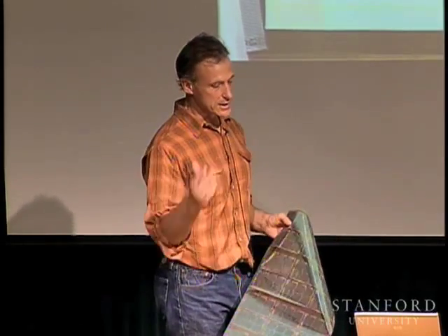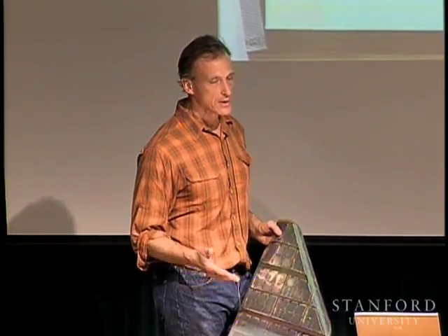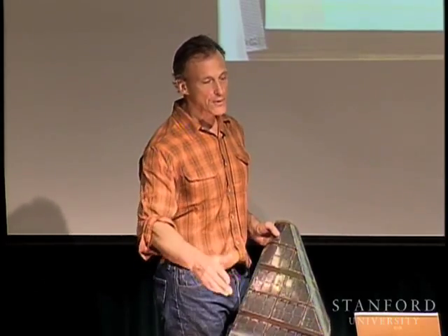Yeah. So wait, masters. Okay, the terminology here. The master is the fundamental thing that we cut into either on a glass plate or on a silicon wafer, and those don't wear out. What wears out is the actual elastomer that we're using to produce the many cyclical impressions. As a target, we've developed proprietary materials that can last for 1,000 impressions, which doesn't sound like very much, but that's a kilometer for us. So that's about a run length.